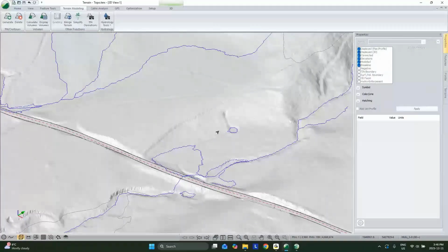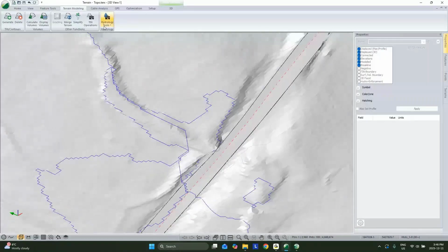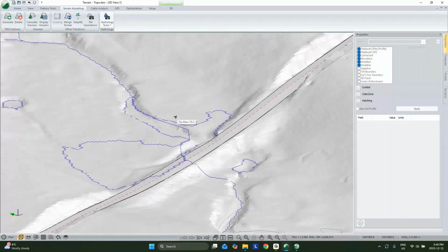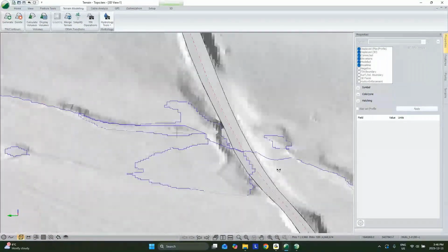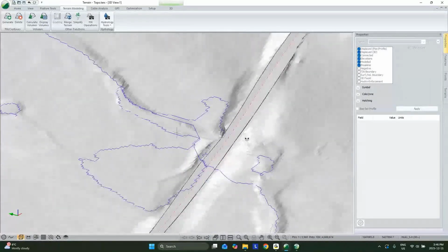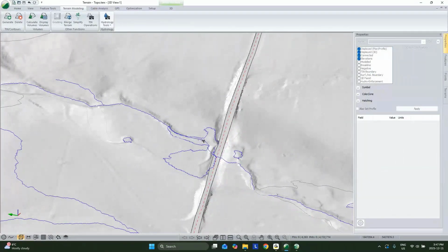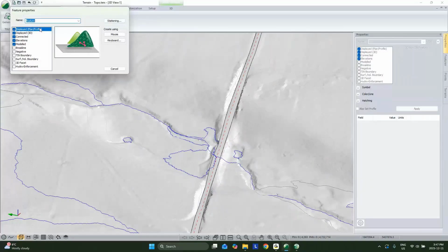Now with this as well, it's a surface analysis. So we're considering the surface as a raster, and the software is going from one cell to the next following the steepest path. And again, setting the stage for what we do in location, here we've got that existing road. It's just looking at the surface. Our water is actually going to probably flow through this thing. So if we added in a hydro enforcement feature, we could do that.